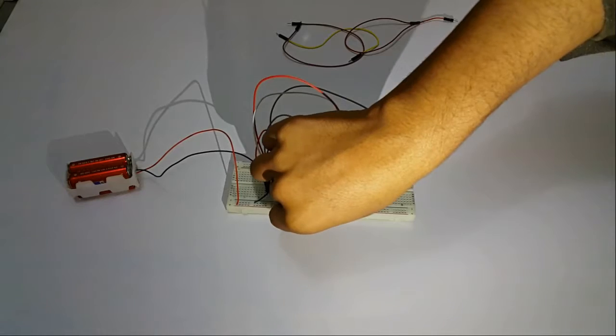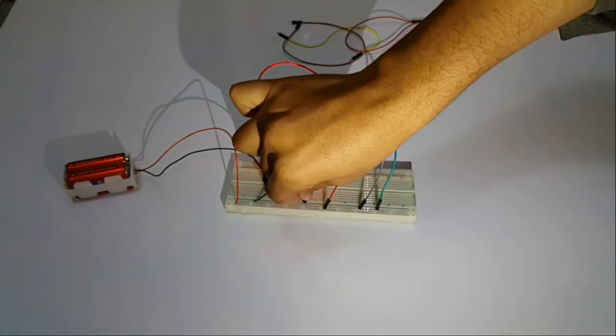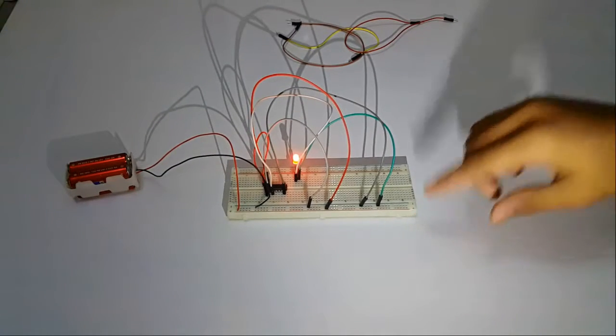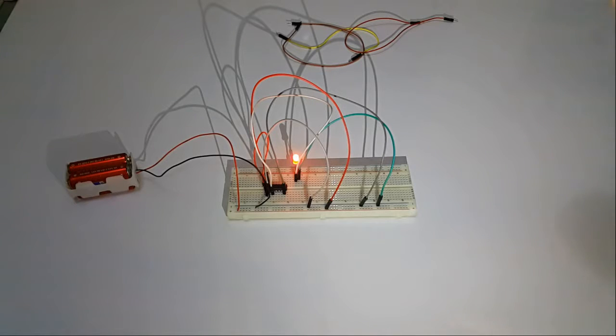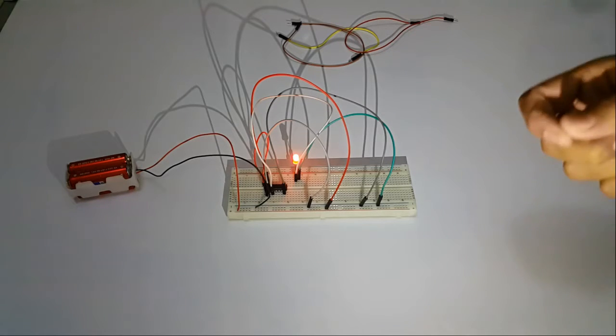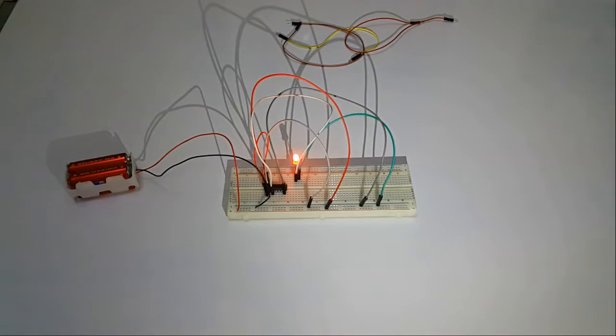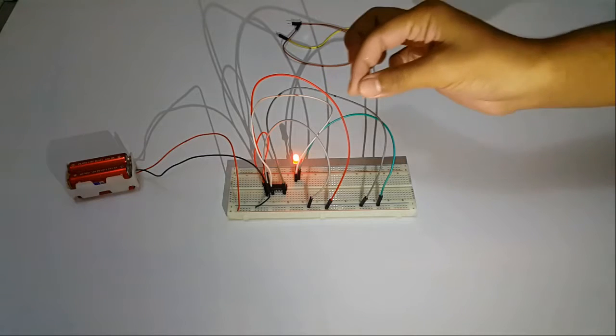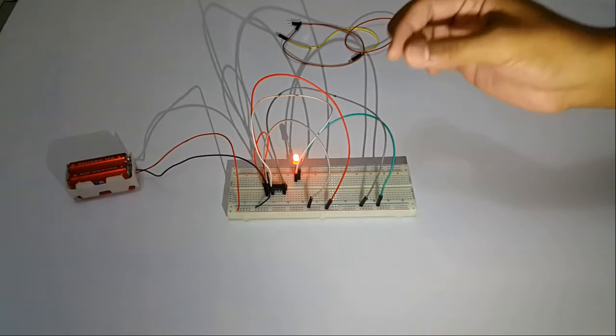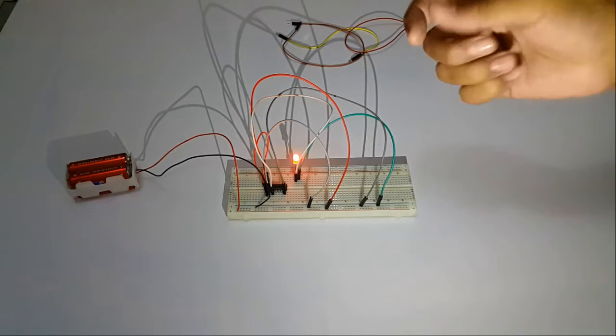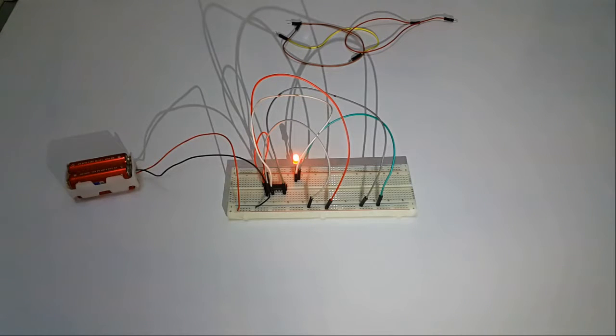Now you see, when I place it here, the LED gets on. Which is the property of the NOT gate, according to which when the input is 0, which means the input is connected with the negative side of the breadboard, the output would be 1, and this LED gets on, which is verifying the condition of the truth table of the NOT gate, that when the input is 0, the output would be 1. So this was the whole phenomenon.